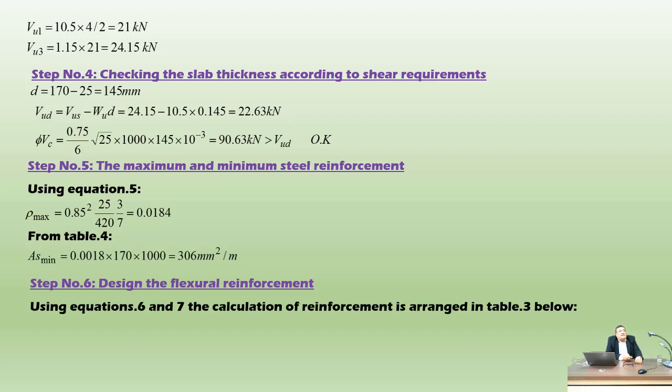That is, the effective depth, which is determined according to deflection requirements, is okay for shear strength.